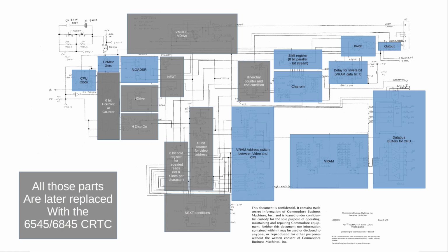And this of course makes it much more flexible, because you don't have to fix timing and so on. You can change the end conditions for the raster line counter. Say you don't have 8 but 9 or 10 raster lines per character. You could have a larger video memory and all that stuff.